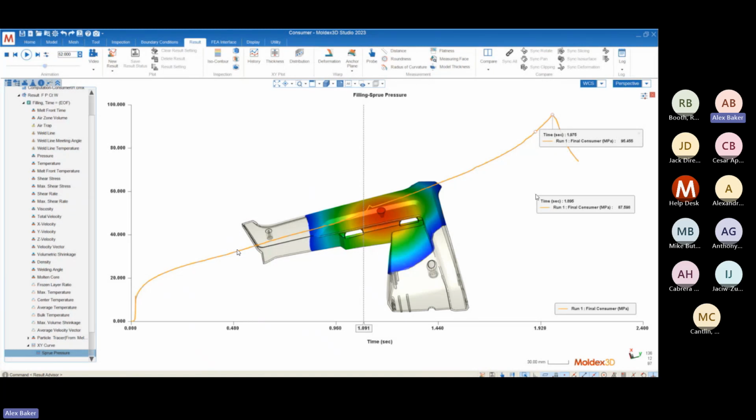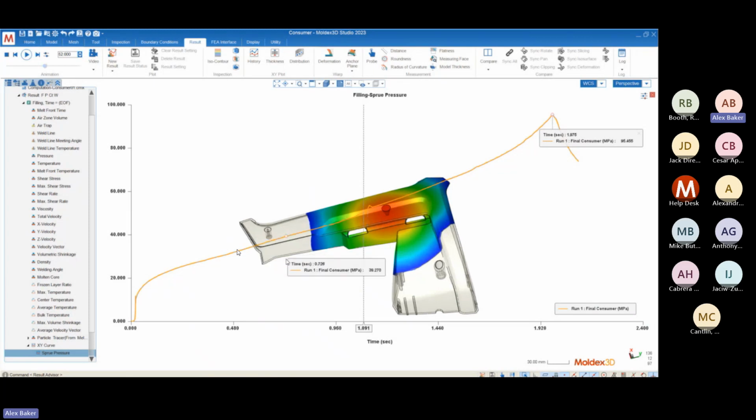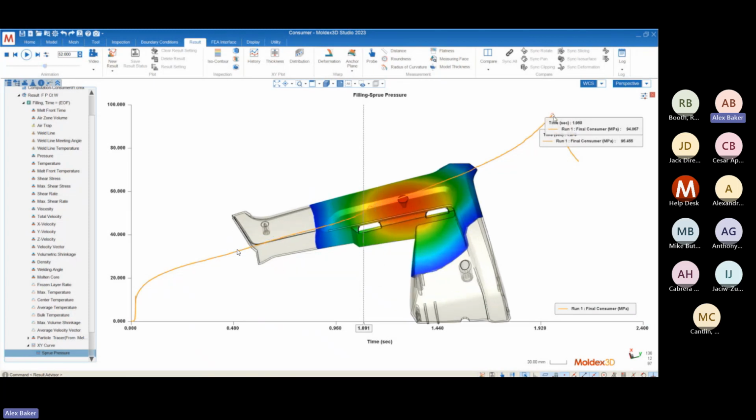which is going to be a large impulsive force on our machine, which can damage our machine and cause the amount of pressure requirement to be much higher than what we would expect. After this VP switch point, we're transitioning to the packing stage, and we're releasing the condition that we need to maintain a constant flow rate.